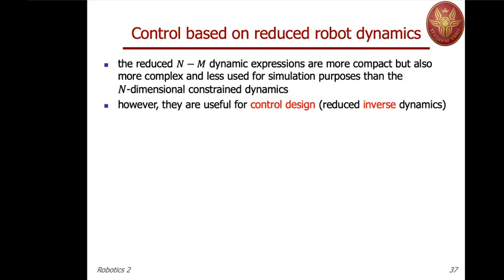In fact, look at the expression of the reduced dynamics, the one in terms of v dot, which is pre-multiplied by the reduced inertia matrix F transpose M F, and look also at the multiplier, the contact forces that arise when you try to violate the constraints.